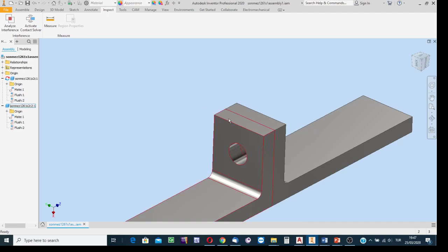Oh, sorry. 16 millimeters is the thickness plus 10, 16, 26. Almost say that 10 more millimeters, 46 millimeters. So in the market the minimum length of a bolt with diameter 10 is, as I remember, 45.